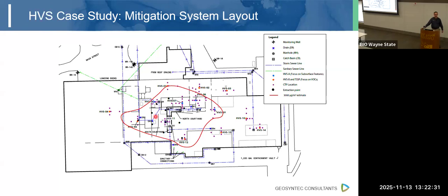Yeah, well, I'll say a couple of things. Yes, we do look into that. I'm actually going in tomorrow to get water samples and vapor samples from a creek drain. As a technical community, I think we're still trying to get our arms around preferential pathways, conduit VI, whatever people want to call it. I don't think Michigan has real specific guidance on that. They want you to consider it and investigate it, but I don't think they give you a sewer vapor screening level to compare to.